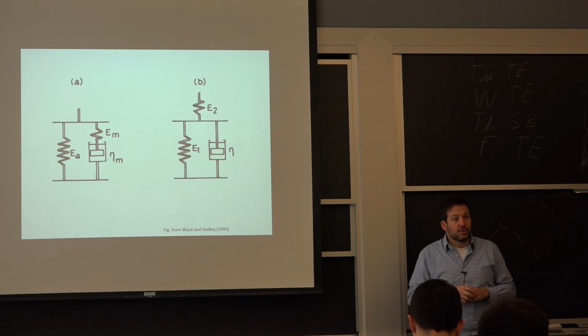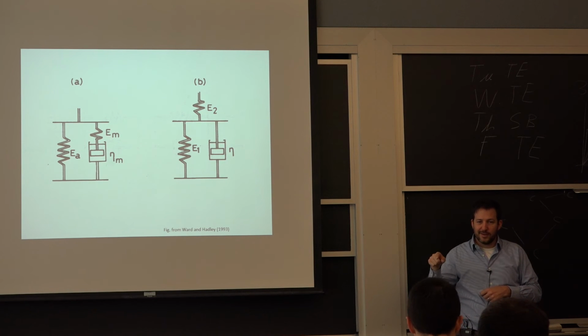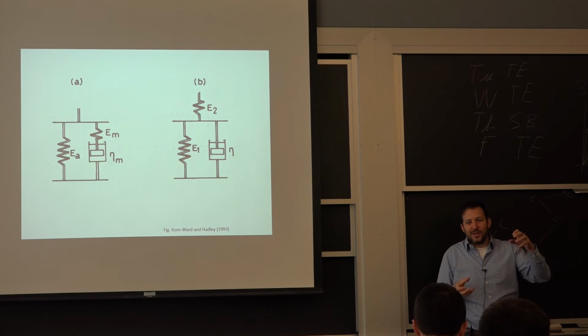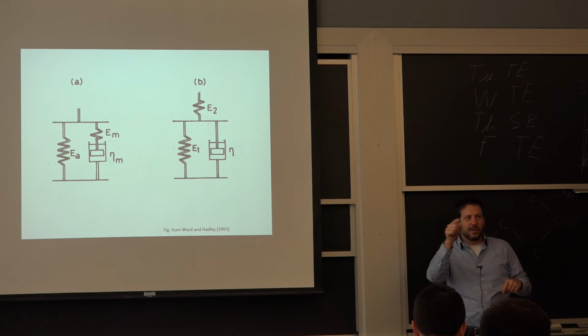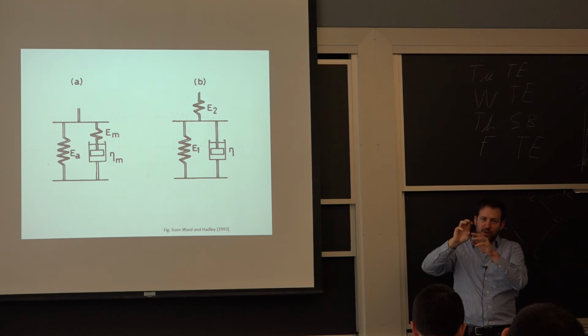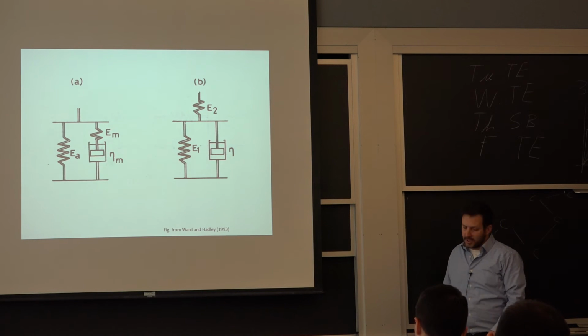Depending on how fast you're cooling, that organization is going to take place at different rates. But essentially, the parts of the spaghetti will sometimes be in the crystal zone or in between. You can't really move the entire spaghetti if it's all mixed in. So what happens is there's a little bit of organization of all these chains that fold back and forth to form that crystal.